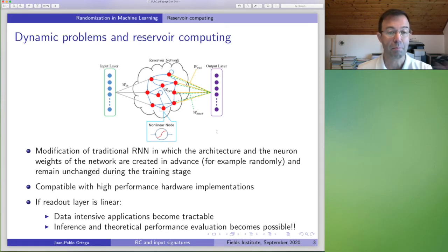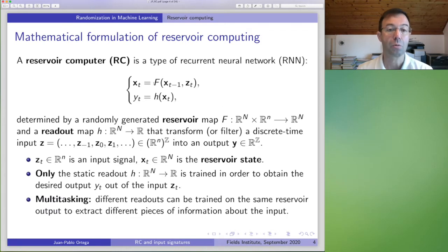So, this is the picture that we always show, but as I told you before, what this means is that we have a state equation. The notation here will always be the same. The C's are going to be the inputs, the Y's are going to be the outputs, and since we are using a state space representation, the X will be the states, right? The states live in a vector space or a manifold which is typically of much higher dimension than the dimension of the input C's and the output Y's, right?